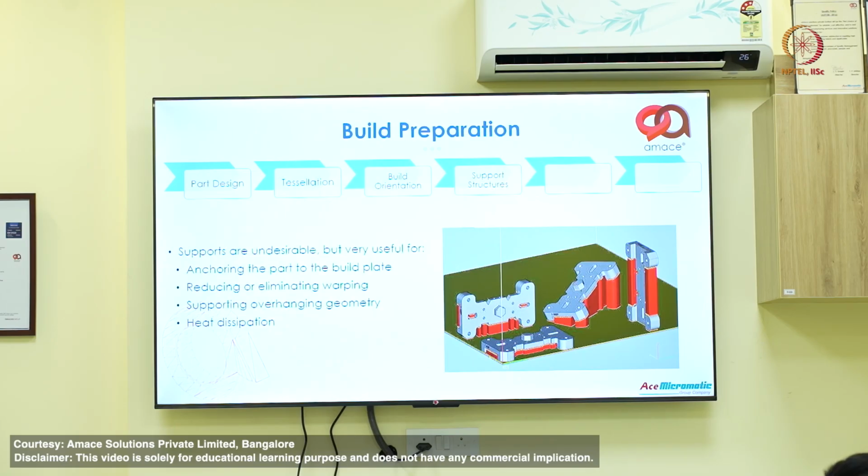In this image you can see multiple parts, actually the same design, oriented in different ways. So there is no standard solution; we need to find the best compromise, because each part has different support requirements. According to our application requirement, we have to choose the right orientation.